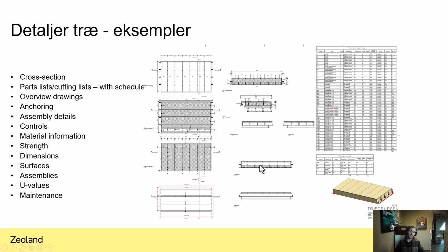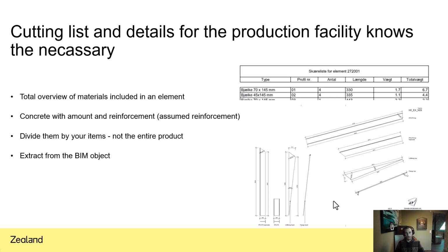Where would you find it important to make a detail? It could be its connection to your glue lam frame, the bottom of a door, the top of a door, for example, and also the top where it hits your roof cassettes. So that includes both types of walls.